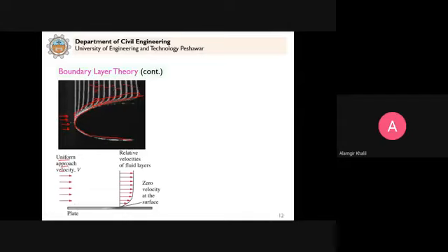But because this fluid flows past this object, at this point on the surface there is zero velocity, which we call the no slip condition, because the fluid which is in direct contact with the surface will be brought to rest due to the resistance, and then the resistance will be transferred to the other layers, and this results in this velocity profile here, because the resistance will be transferred in this direction.